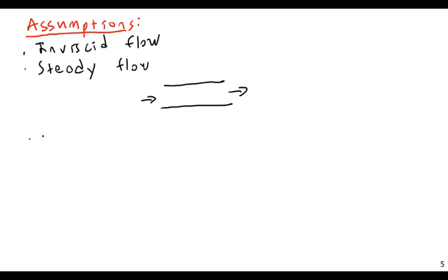We're also going to assume incompressible flow, at least when we're dividing by velocity and using gamma and things like that. Bernoulli actually does assume incompressible flow. I think I might have said earlier that we could use this for compressible flow, but actually I don't believe that would be appropriate for the way we've derived it. You could modify it for a compressible flow, but not for the way we're using it.